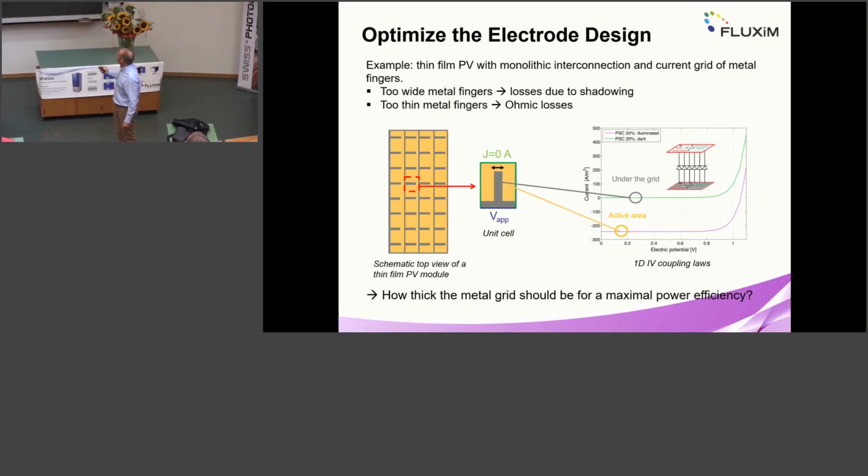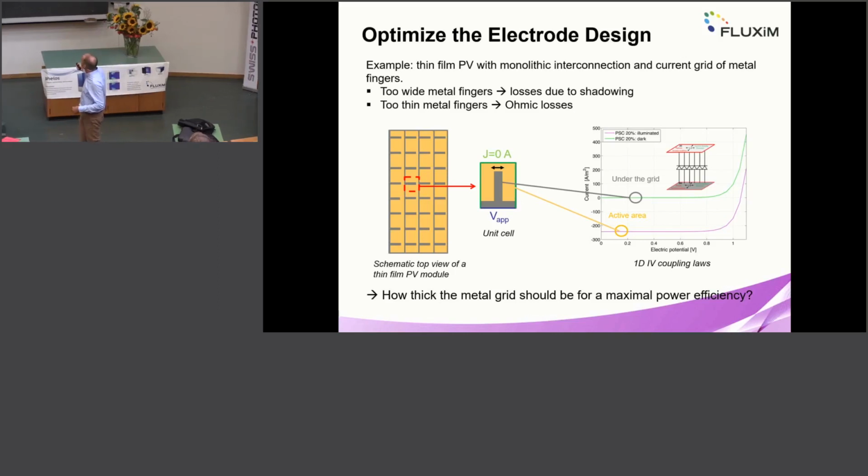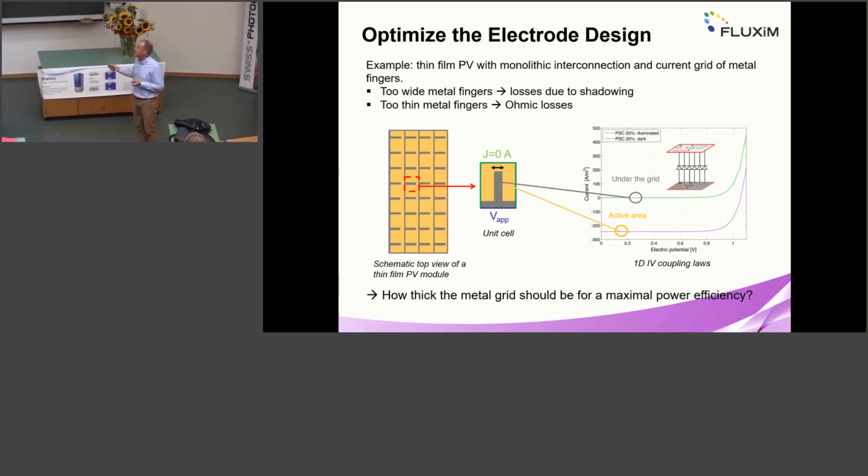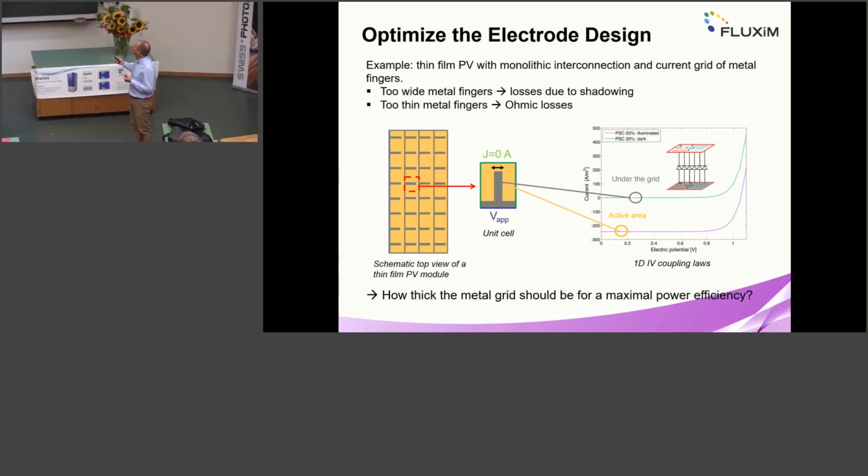So in the software we would apply on the left hand side this gray metal. We would now tilt it in the graph by 90 degrees. We would apply voltage here, and then the green is just a natural boundary condition where we have no current flowing directly from this outside, but the current will be coming from below because the semiconductor layers are below this rectangle. So we need to tell the software what is the JV coupling law between the top electrode and the bottom electrode.